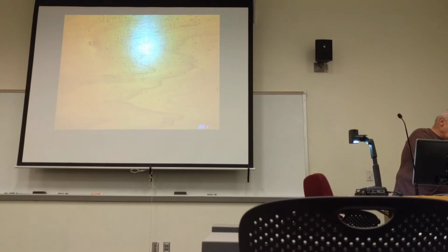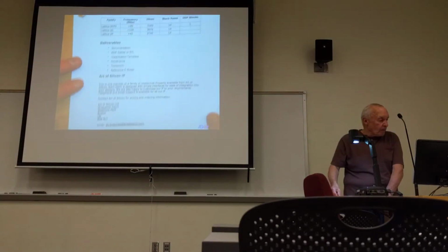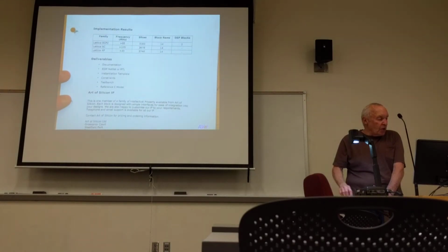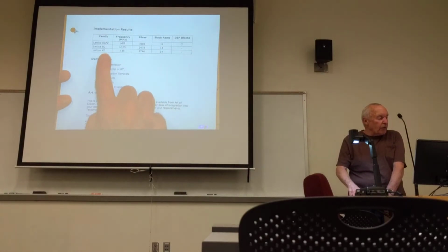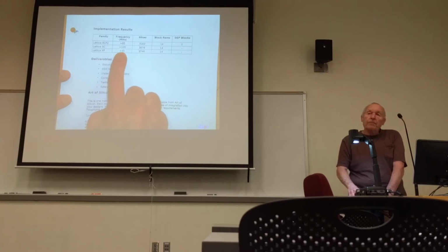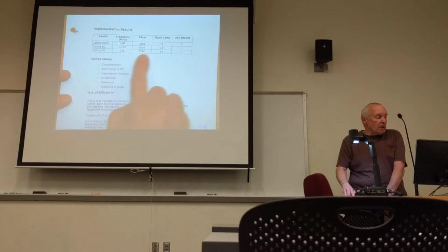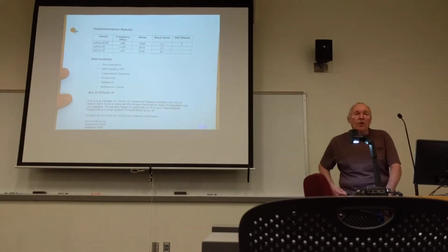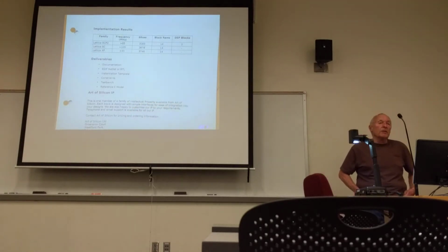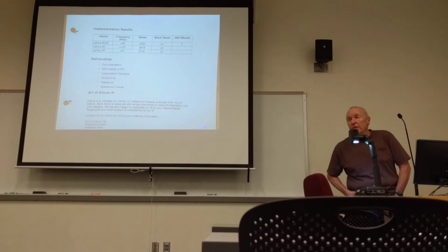Something I found particularly useful is they show you for various Lattice FPGAs the frequency that you can expect this thing to operate at, and it tells you how many slices, block RAM, and DSP blocks are going to be required to actually implement this JPEG encoder decoder.